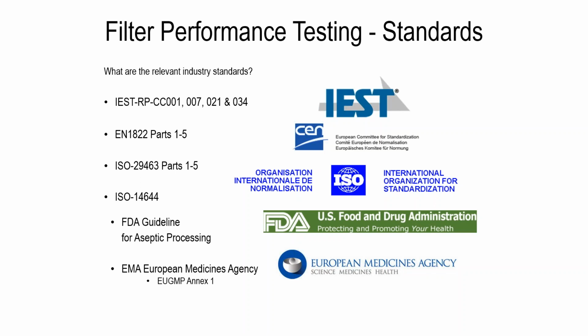So there is bypass, there can be bypass, there can be compromises in the material of the HEPA. As a result of that, we test once filters get into play, just to make sure that the media efficiency is maintained after it's been installed.